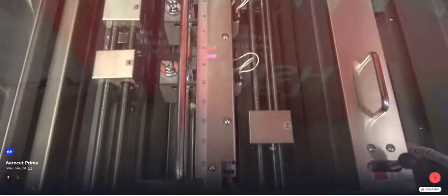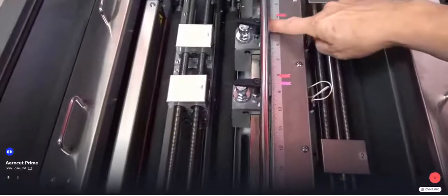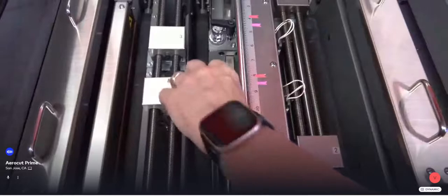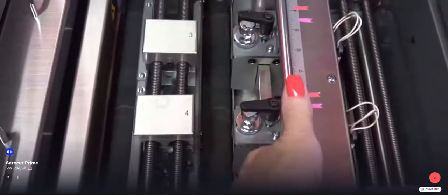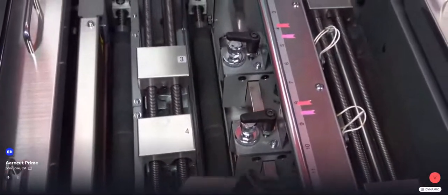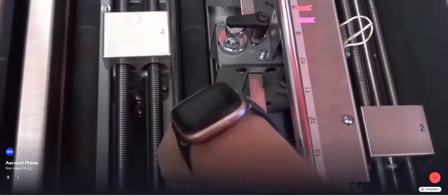To set the perf unit, let me get rid of these tabletops and open up my system so you can see. These are the perf units here. To adjust them, you simply loosen and then move the units. They do need to align, and I think we can get this on the camera, the little blades down here do need to align with these plastic wheels.